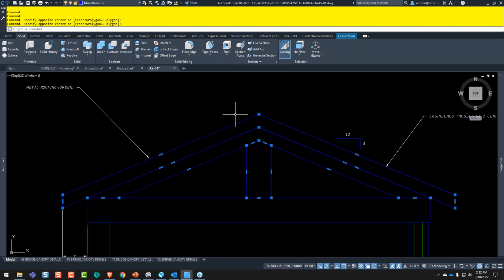So I'm going to do a Control-Shift-C because I'm going to grab it from a specific base point. Control-Shift-C is copy with base point, if you're not familiar. I'll grab this right here because we don't have that point yet. Actually, I could have just grabbed that point there. In fact, let's do that again. Control-Shift-C, because I've got that point. I have this one right here.